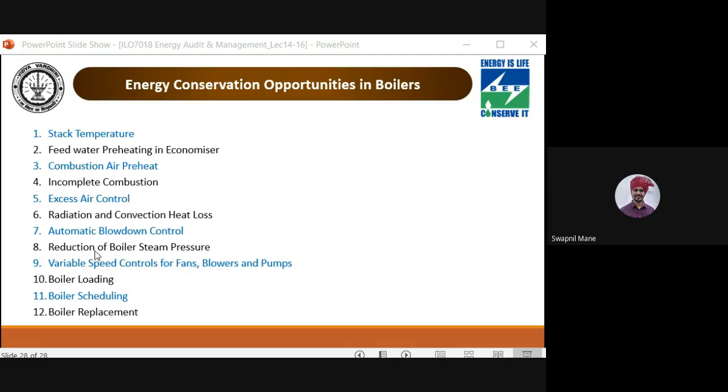But if we increase the boiler pressure, then the option of cogeneration will be available. If I increase the steam pressure, higher pressure steam can be expanded first in the turbine to generate electricity, and then this expanded low temperature steam can be used for process utility. It has been found that increasing the boiler pressure and using a cogeneration system is always advantageous and efficient.